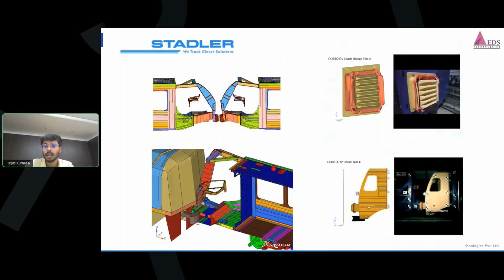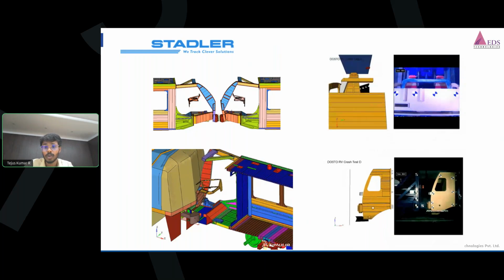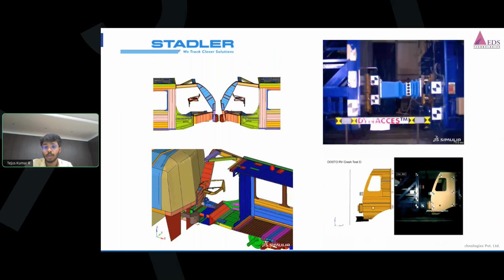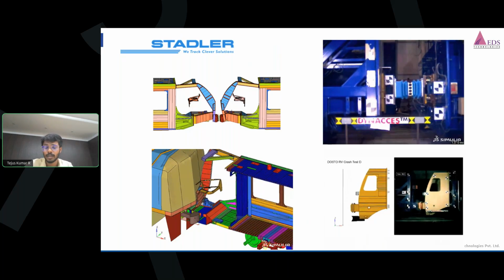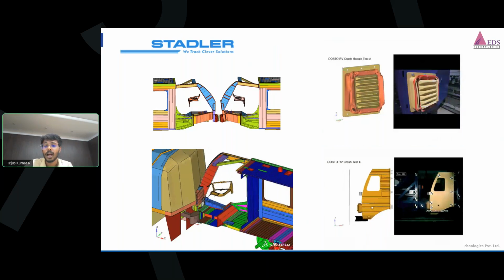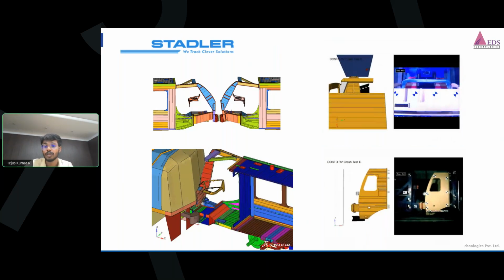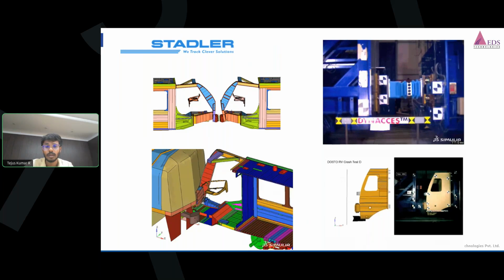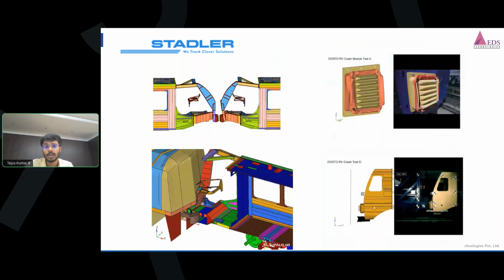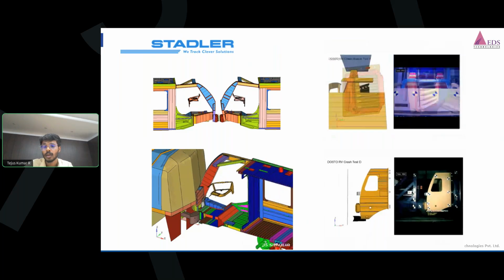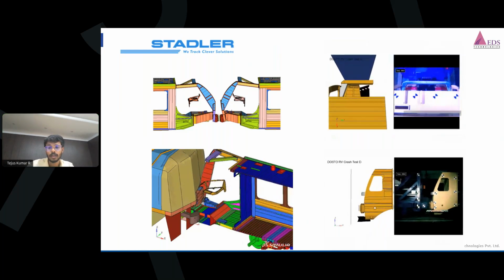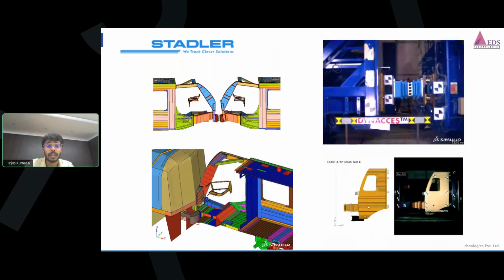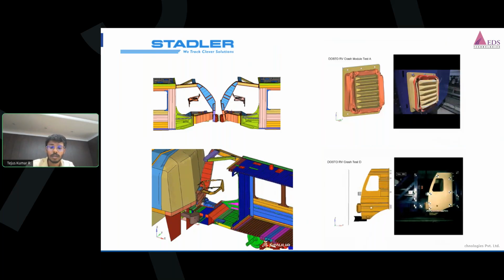One of the greatest advantages is that simulation engineers can visualize exactly how the energy flows through the structure before building hardware. You can identify which component deforms first, whether the passenger survival space is maintained, and whether the crash module absorbs sufficient energy. Also, when you compare the virtual and physical tests, you can look at the accuracy of the software and how it predicts the highly nonlinear interactions.